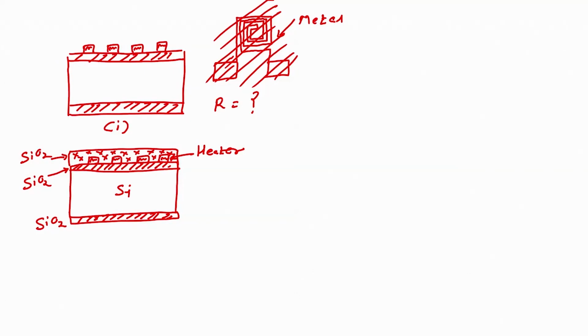But how can I measure the resistance? If I remove the insulator from the contact area, this is contact area, contact pad, if I remove the insulating material from the contact pad, then I can tell whether I can take a proper contact or not, or I can measure the resistance in a simpler word.